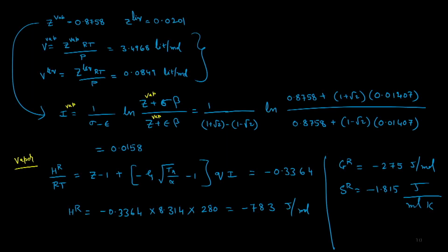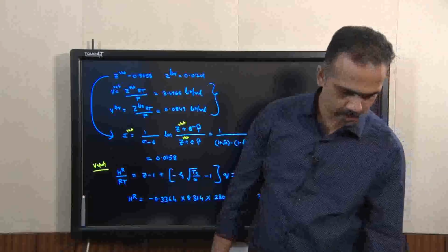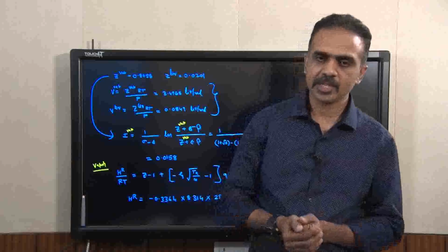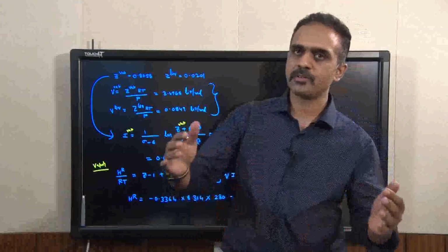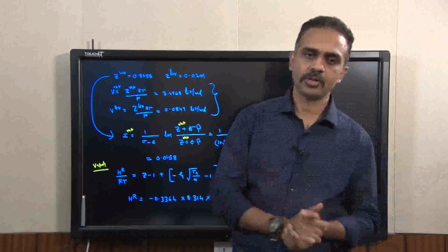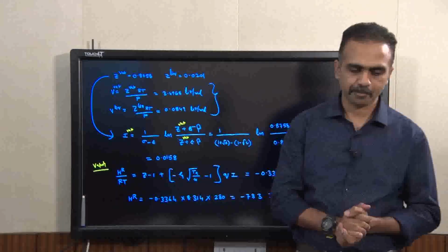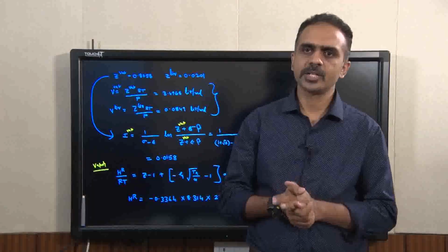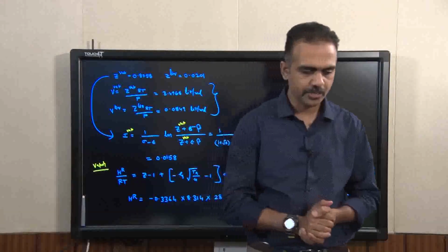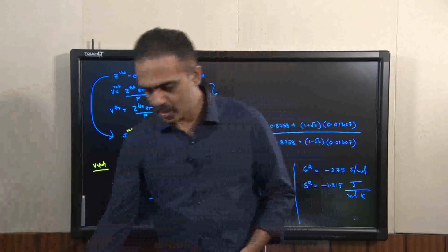Right. So this is how I will use a cubic equation of state and calculate various residual properties. We have looked at how we can derive the expressions given a cubic equation of state or use the generic expression, the one that is readily available for the 4 different cubic equations we looked so far. So this ends our discussion on using cubic equation of state for residual property calculations. What we'll do next is look at what are known as Pitzer correlations.